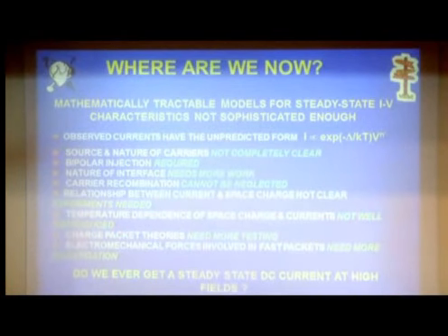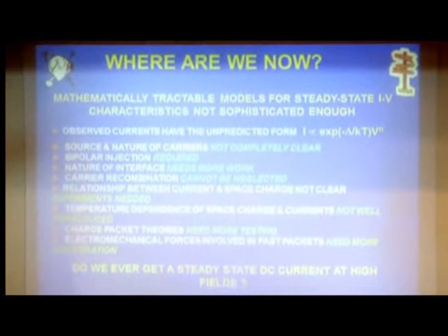One of the features you find about all these all-singing, all-dancing computer models, they fit perhaps two different experiments simultaneously. The conductivity experiment and the space charge experiment. But they fit it at one temperature. You change the temperature and the space charge is nothing like what you see. Charge packet theories. We need some more work. Fundamental work. Not, I've seen a charge packet and it does this, but I've tried to model the charge packet and I predict it does this.